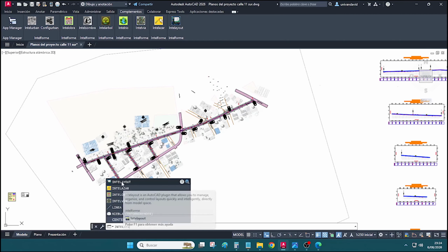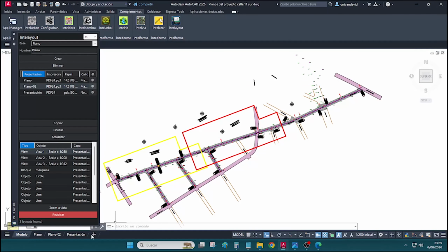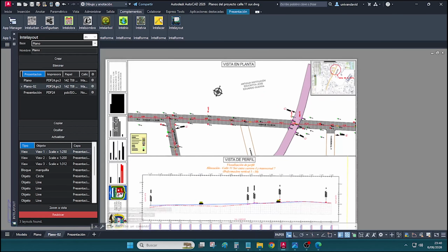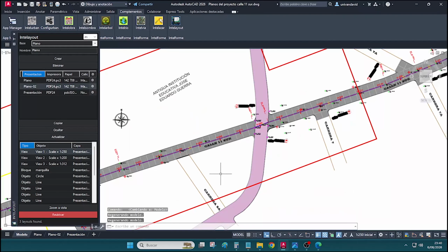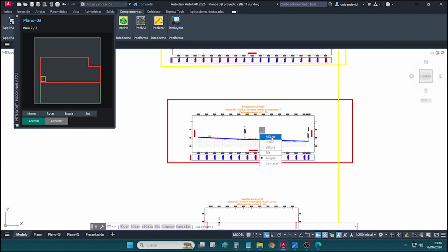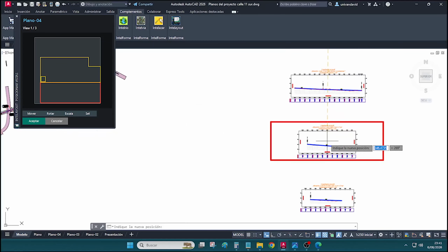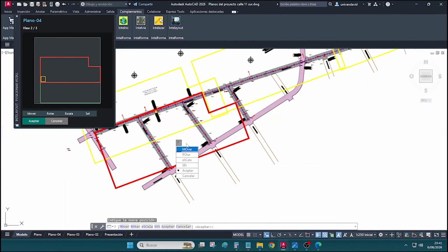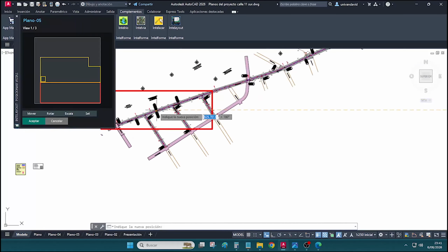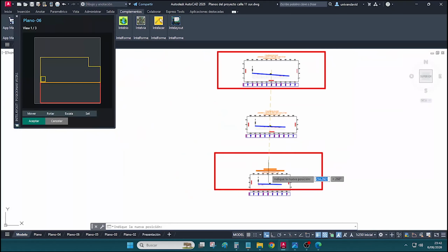Alright. Intelayout revolutionizes the way we work with AutoCAD layouts, letting us manage all our layouts from a single palette and control their viewports directly from model space. Its main advantage is that the user can physically see, right on the model, the area corresponding to each layout and modify it dynamically, quickly, and smartly. This is super useful, especially in linear projects, big projects where you get a lot of layouts. From there, we can move, rotate, scale, and relocate the viewports, avoiding having to constantly go into each layout to make these tweaks.